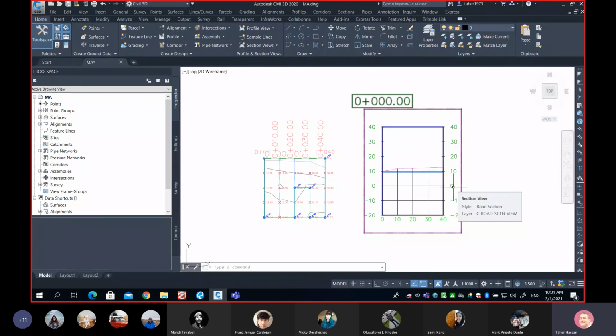Then, if you need to edit them, go ahead and edit them to make them good surfaces. Then it's as simple as this: here is surface number one, called the base surface. Here is surface number two, our comparison surface, and the software can find the volume for you. We discussed already that this is a good method.